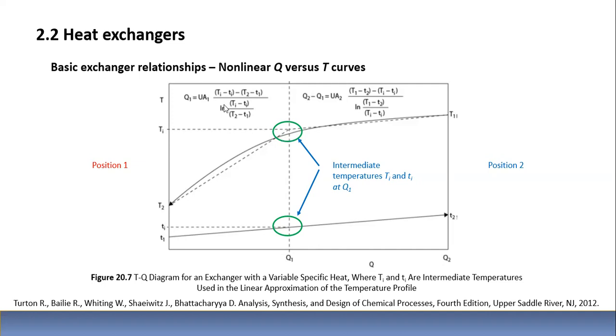In a counter-current configuration, that will be Ti minus ti, because this small ti is the temperature of the cold stream leaving the exchanger on the same side, and on this side we will have T2 minus t1. So the natural log will be of Ti minus ti over T2 minus t1. So this will be the procedure for the LMTD in a counter-current configuration,